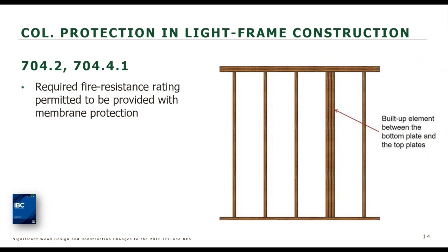One question that we get and have gotten in the past quite a bit is, what happens when we have a post or built up stud in a fire resistance assembly? Does it need to be encased? Some say, since it's a column, it does need to be encased. Well, in light frame construction, that's not really the case because our major structural system is based on a bearing wall system. We're not based on a post and beam type construction where there's not a lot of redundancy. It's a light frame system with bearing walls.